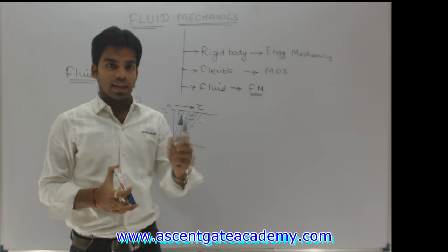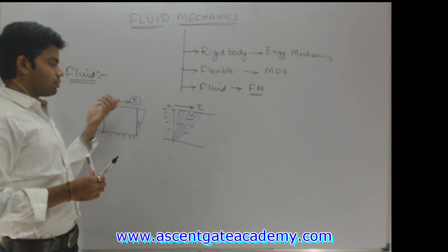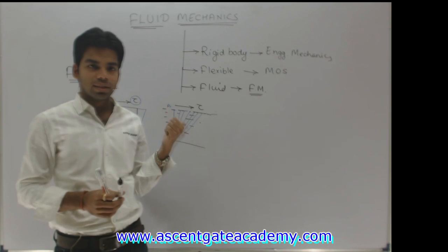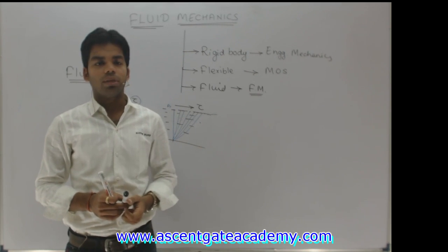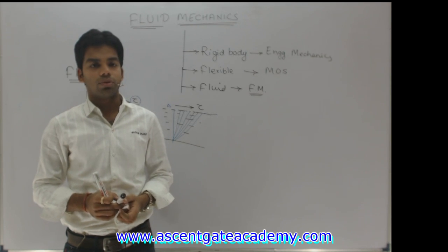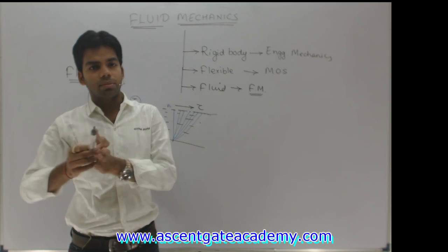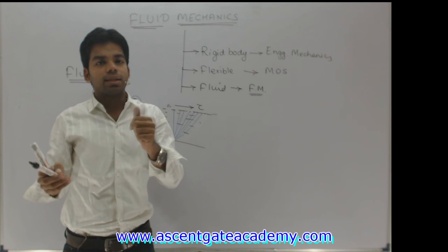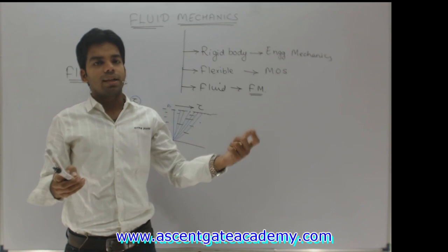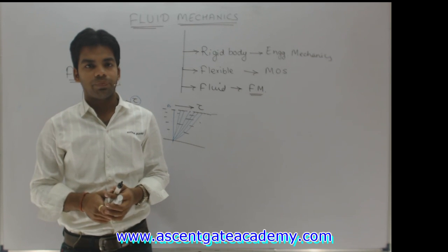That is the first thing. Second thing, as I told you, if a shear stress or shear force is removed from the solid body, the solid will regain its original shape. The fluid does not regain its original shape on removal of shear stress or shear force. So we can call the fluid a zero memory substance. Solid has a memory that it regains its original shape. Fluid has no memory. Once it gets deformed, it never regains its original shape.